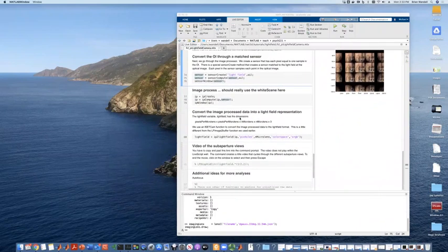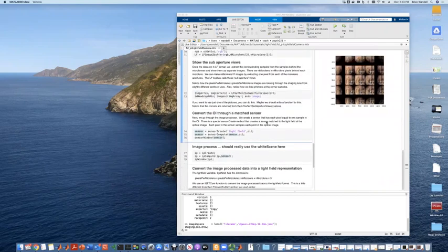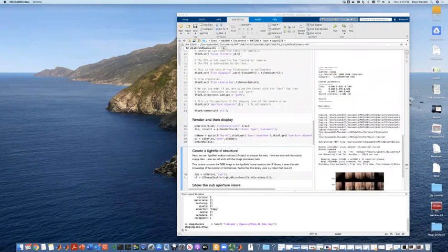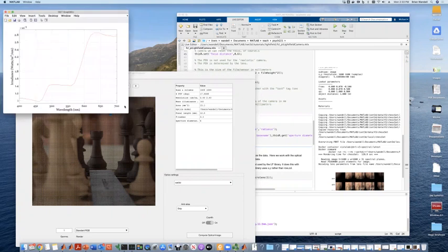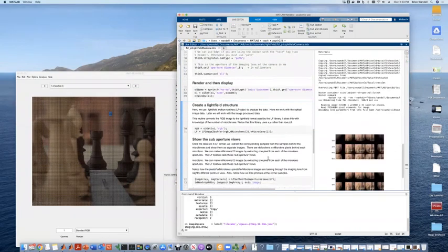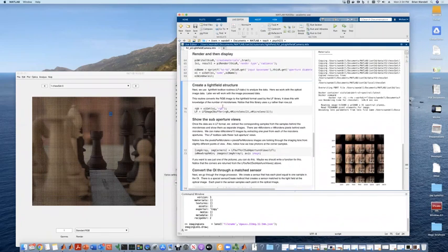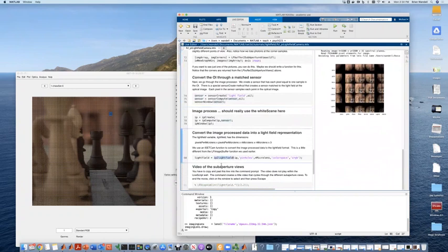I have a question, Brian. Before, you showed the optical image as a representation at every wavelength, so you have an image for every wavelength that you're sampling. And then you generated the aperture images, and presumably that would also have a representation for every wavelength. So could you now generate a similar image for the processed one? And you always do that, generating that aperture image after you demosaic? Yes. In fact, that is what I'm going to do right now. Okay. Just what you said.